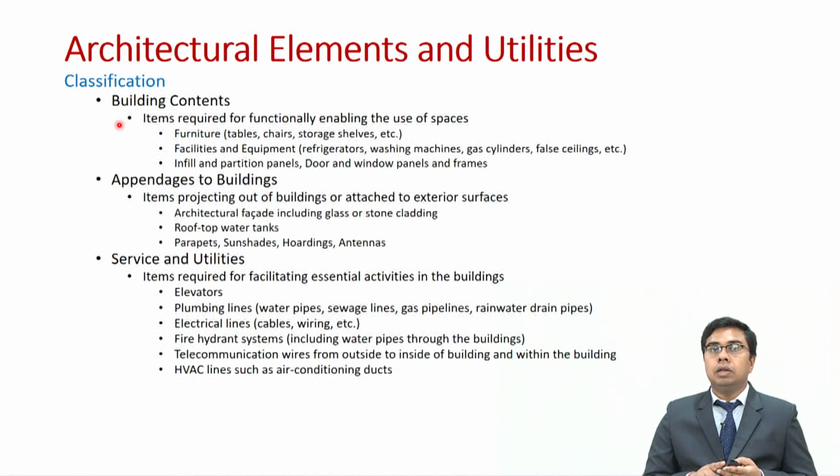In particular to reinforced concrete or steel buildings, you will find that the infill or partition walls do not carry any load. So, in that case, they cannot be classified as structural elements, because failure of these may not lead to the collapse of the structure unless it attacks a structural element so badly that the structural element gets damaged. Similarly, the door panels, window panels and frames are also not part of the structural components.